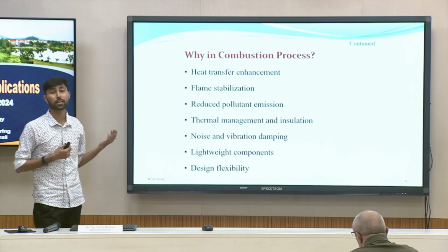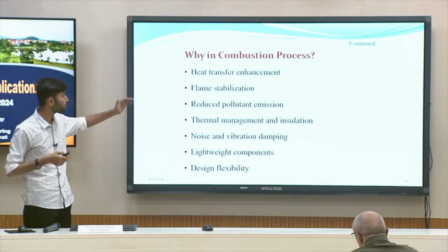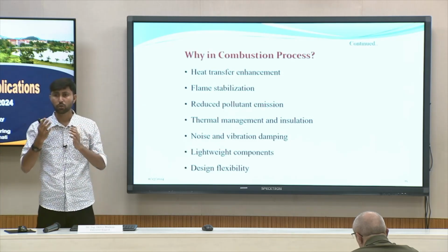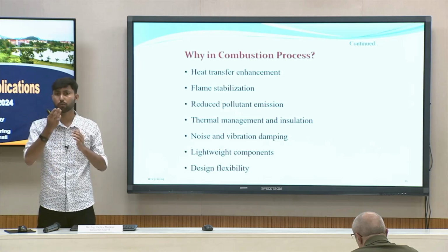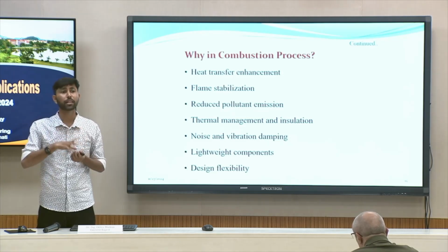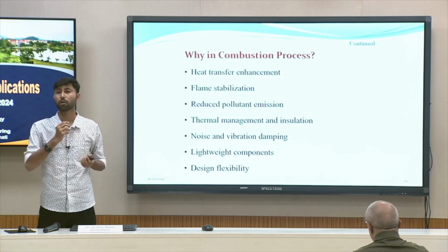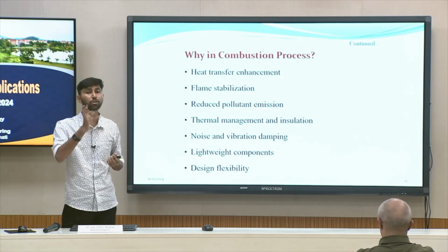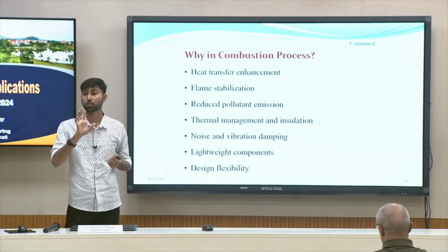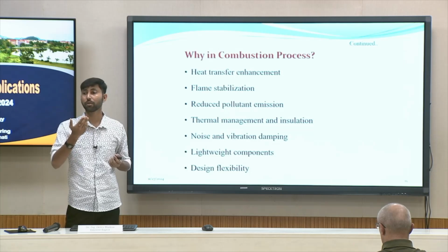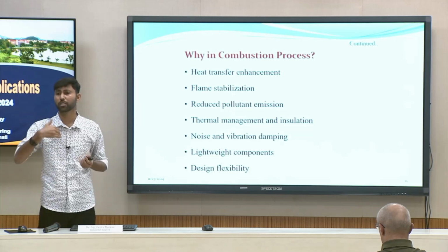It gives flame stabilization. As you have seen, this metal foam has an intricate shape. So when the fluid flows through it, it will create turbulent flow. It is not a laminar flow, it will create a turbulent flow. As a result, proper mixing of fuel and air takes place. Because of that proper mixing, combustion will take place almost completely.